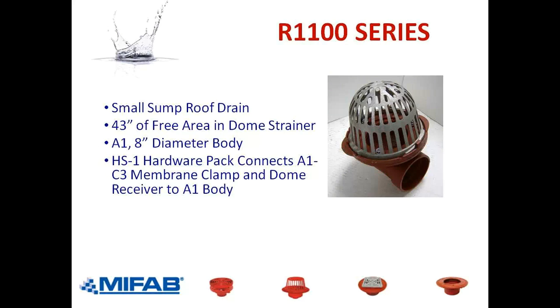When you place it in the ring and turn it, maybe an inch and a half to the right, there's a sliding guillotine, for lack of a better word, impression on the outside of the dome that will lock into the tabs of the A1C3 membrane clamp.